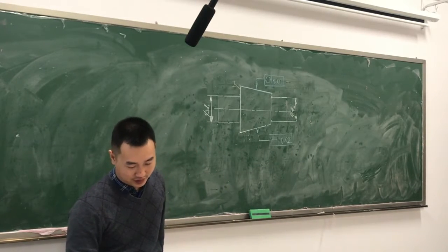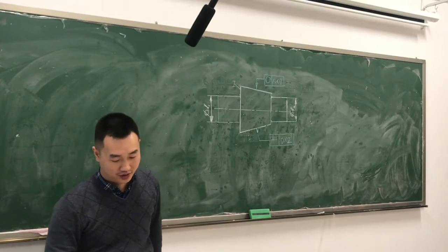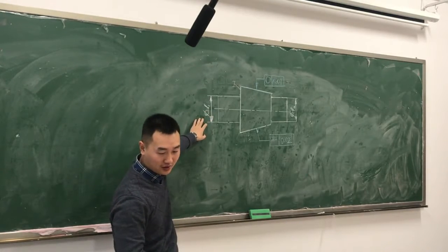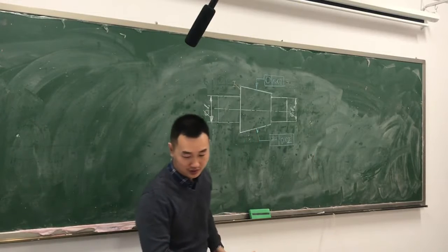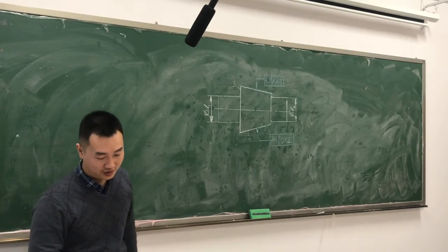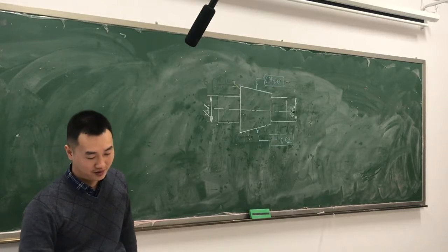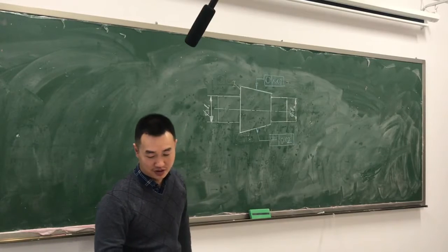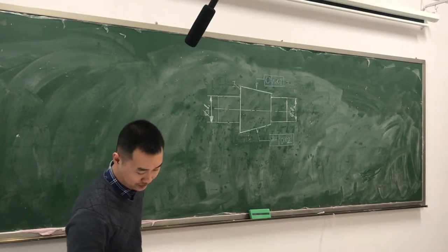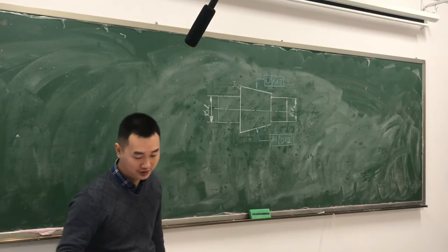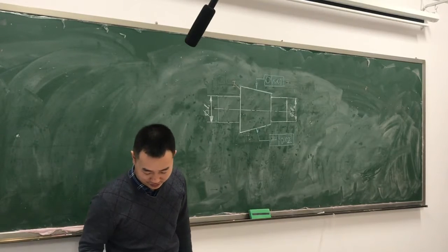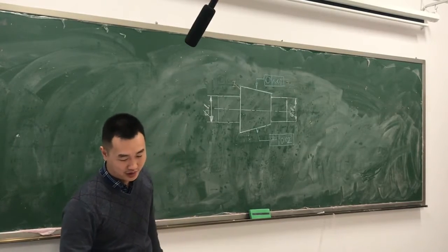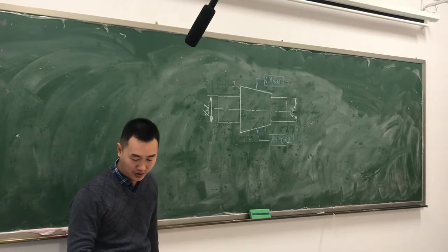And the next one is the concentricity of the axis of phi D1 cylinder and the phi D2 cylinder, with the common datum straight line of the D1 axis and the D2 axis, 0.005 millimeter respectively. So this is how we label the concentricity. If you do not know how to label it, you can turn to page 101 for help.